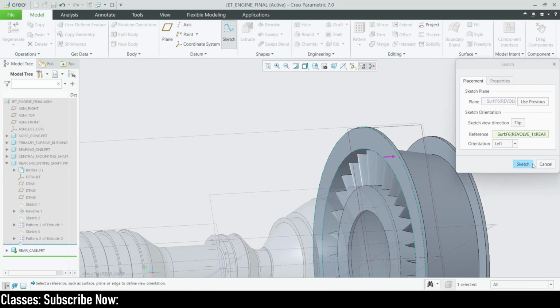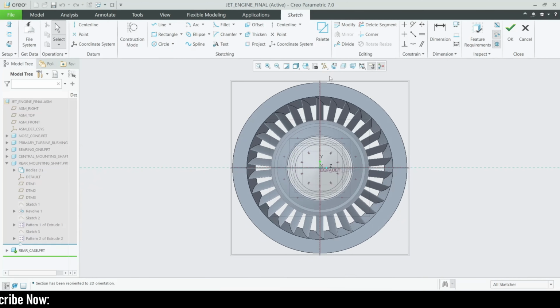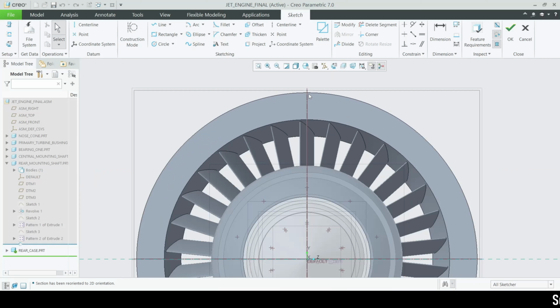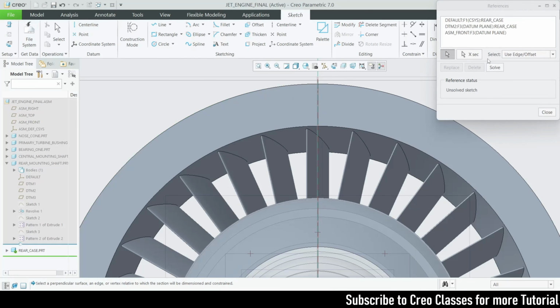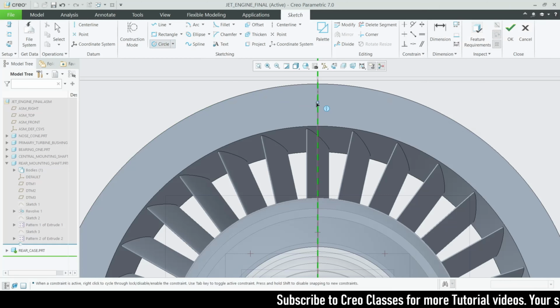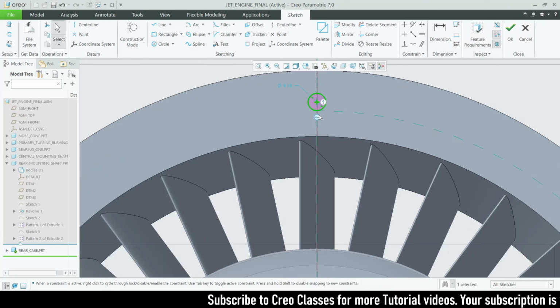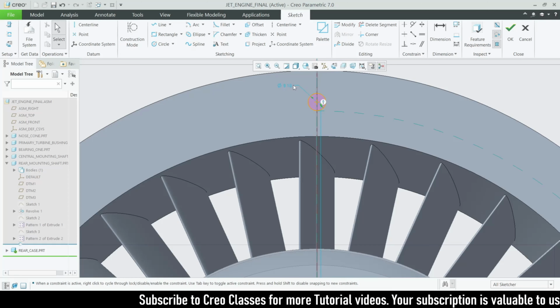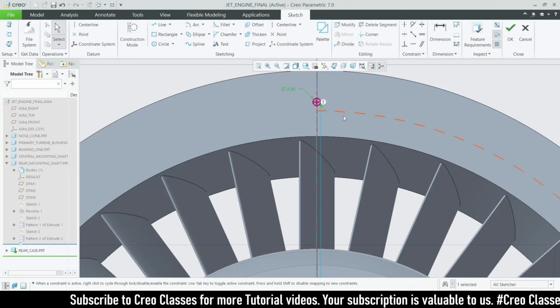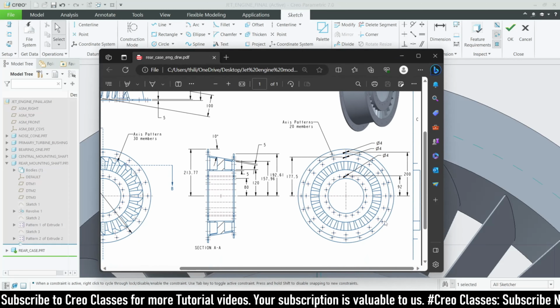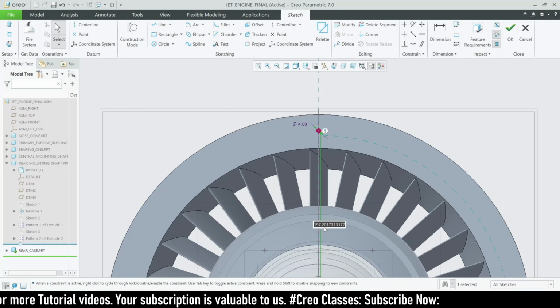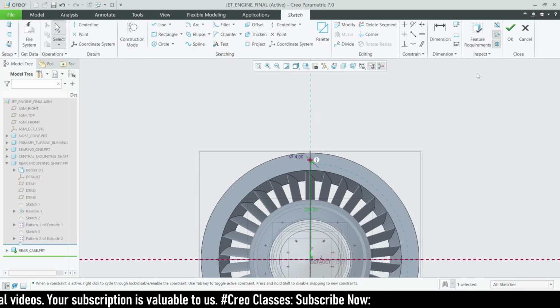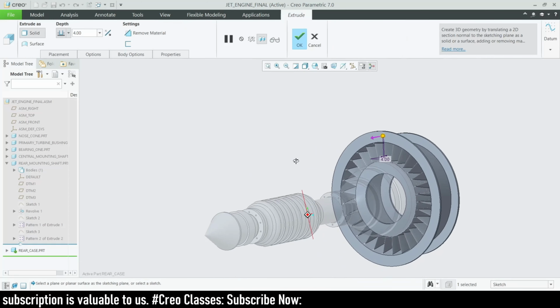So now we can go for the sketch. We can select this surface, sketch, and then let's go for the sketch view. Okay, so for this surface, I'm going to draw a circle at this reference. We don't have a reference, so I'm going to click this as a reference, solve, close, and then I'm going to create a circle here. I don't want to make any coincident relationship. This diameter value as 4, yeah, 4, and this height as 200. Okay, click on OK here, extrude.